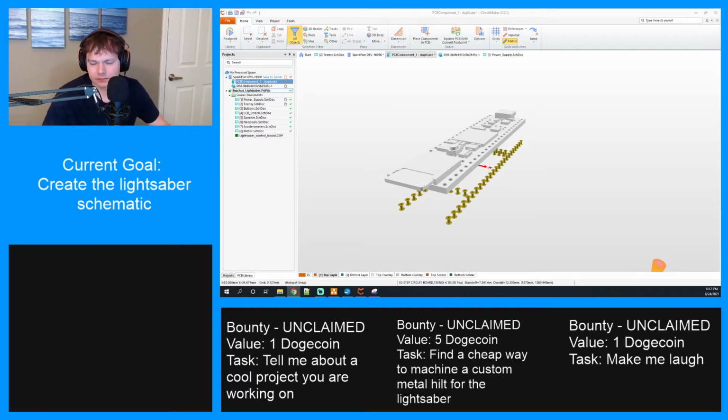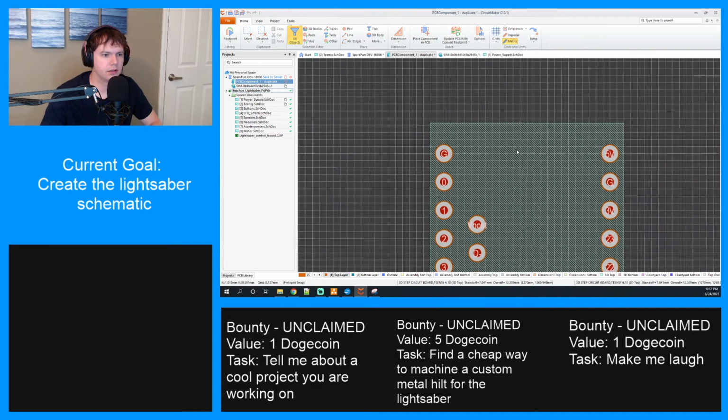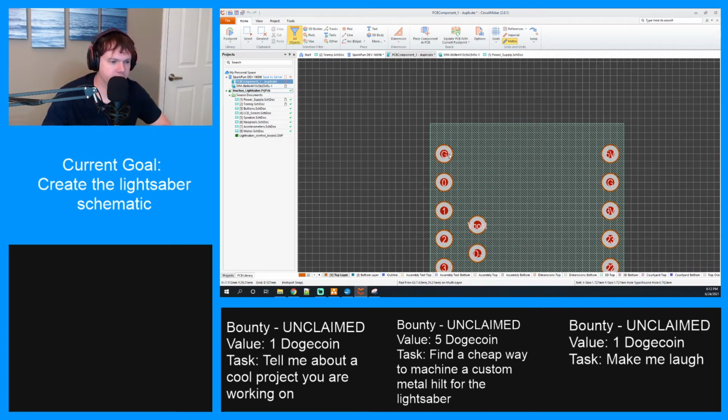Okay. So we need to add vias for the pogo pins. So we can just use the same size and just position them correctly. And I think that would be best. So let's go back to the 2D version. Oops. All right. And then pad, copy, paste, one there, one there. Okay.